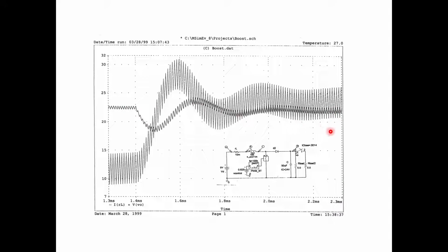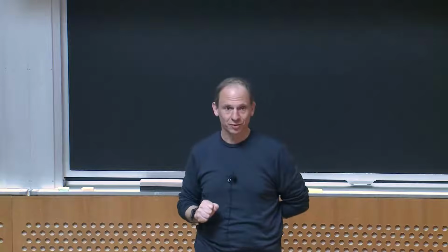Well, I'm not particularly interested in this switching ripple, right? Why am I not interested in it is because notice that the dynamical behavior is at a very low frequency compared to the switching ripple, okay? And I can't really do anything about the switching ripple anyways, right? In other words, that's intrinsic to the converter, right? I'm going to put some energy in, I'm going to process it through, I'm going to take it out. If I'm trying to, say, vary my duty ratio on the time scale of this switching, I'm very, very fast, I'm probably going to make the converter do unhappy things, right?